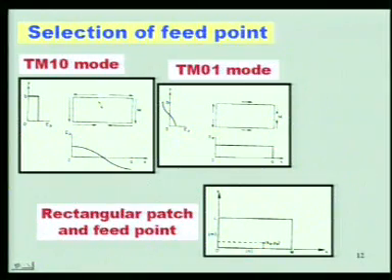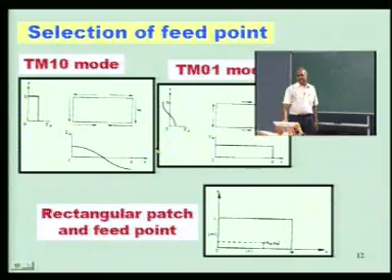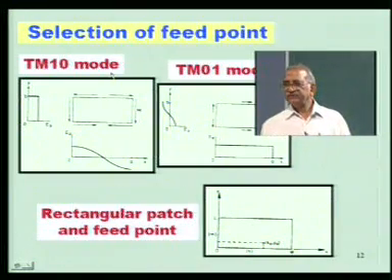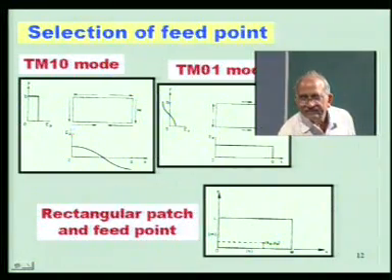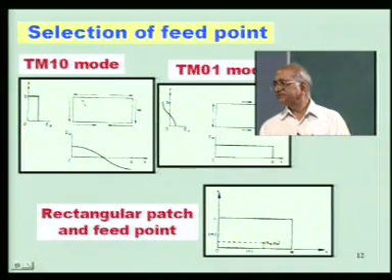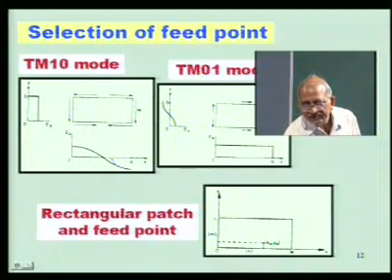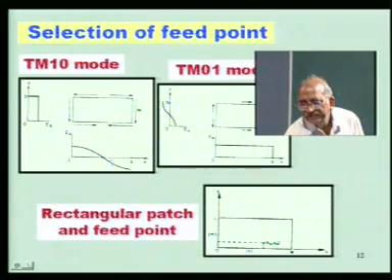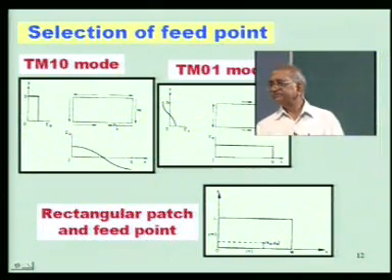Okay. And wherever the electric field is 0, the impedance is going to be 0, and wherever the electric field is maximum, that is at this edge, the input impedance is going to be high. So much so that for typical dimensions of the substrate you use, the impedance at these edges could be something like 400 ohms, whereas it is 0 here. So, the impedance varies from 0 here to 400 here and 400 here. In between, it is going to be somewhere 50 ohm.